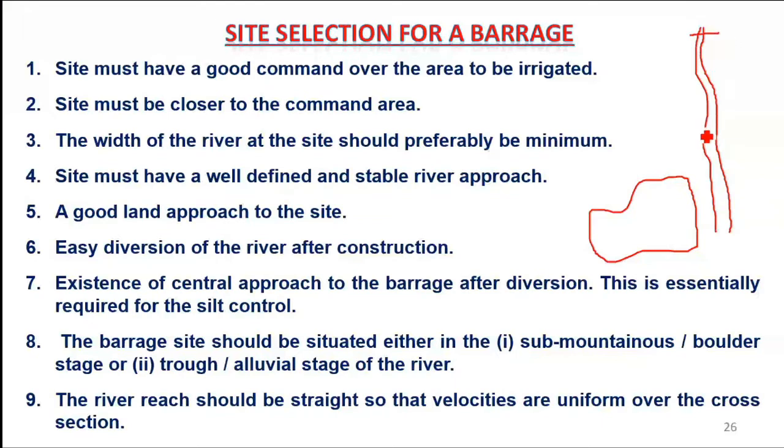Here or here? Which side would be better? This is site number one. This is site number two. Site number two should be closer. What would be the benefit? There would be less seepage, less evaporation losses, and less seepage losses within the canal network.